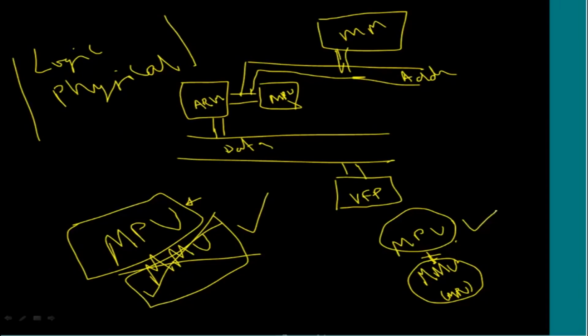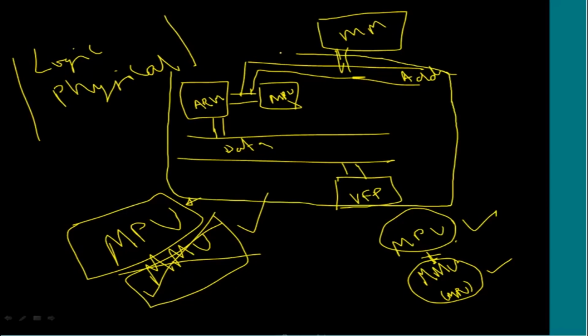Again, the option of having an MPU or MMU is the designer's choice. If the system you build does not need virtual memory support, but needs only memory protection unit support, then the choice will be to take only this module and not bring in virtual memory at all.